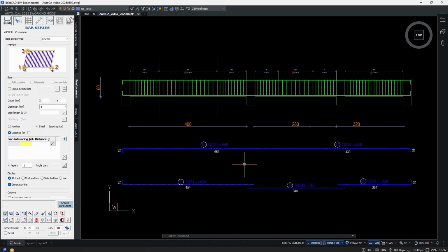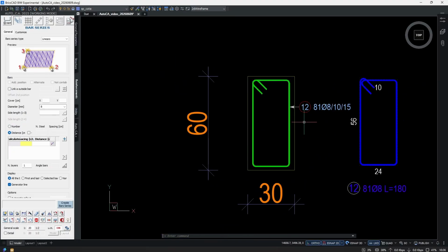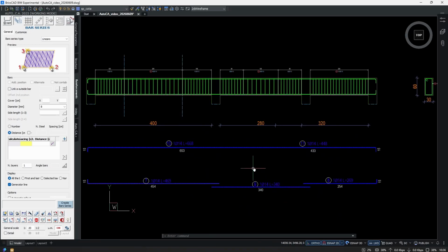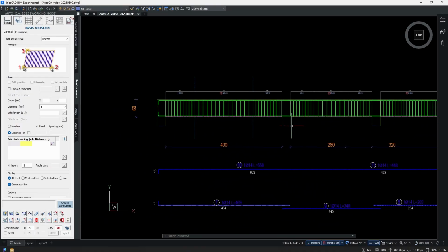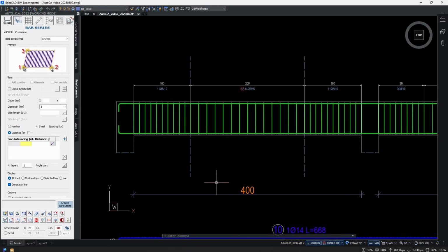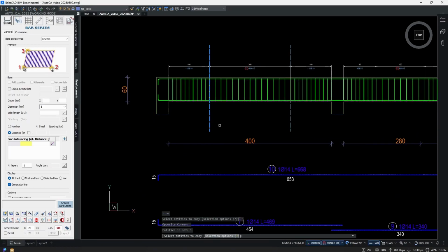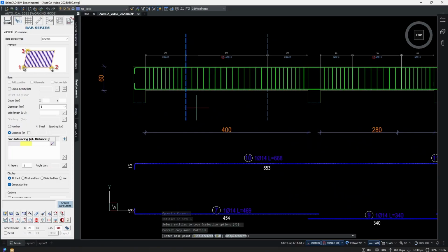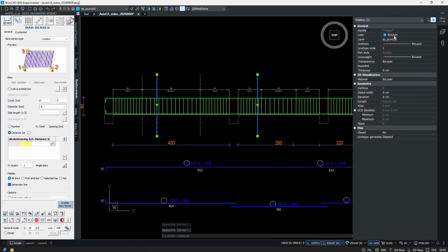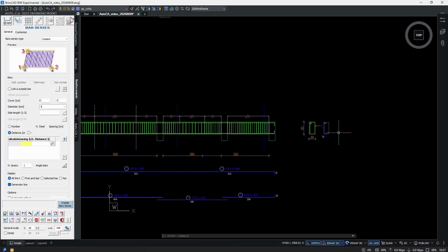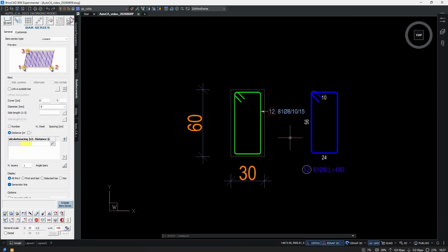Now the thing is, we have multiple options to make these longitudinal bars represented in the cross section. I'm gonna show you all these options. First, let's create characteristic sections. What does it mean? Well, we're gonna create cross sections in multiple places, like here, and also here. I'm gonna give these section lines another color. So it means that we will need multiple inside stirrups as well.